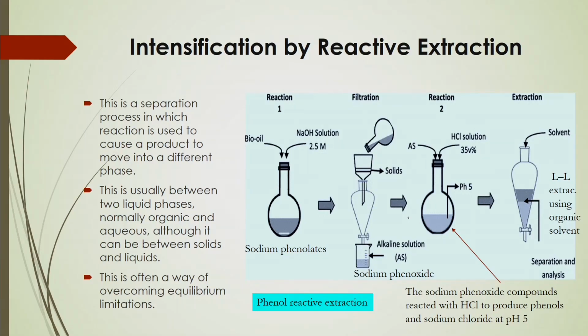So, if you integrate reaction as well as extraction, you can use reactive extraction systems, where you can get intensification of the separation process as well as reduce the unit size, with simultaneous occurrence of the reaction and extraction. The process is also energy efficient, and you can overcome the equilibrium limitation of the reaction.